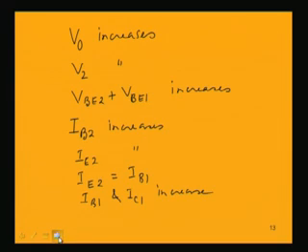So the ultimate effect is that the load current IL decreases, so V0 decreases. Initially V0 increased, but finally V0 decreases, which means it is kept at a constant value. So this is one type of shunt voltage regulator.